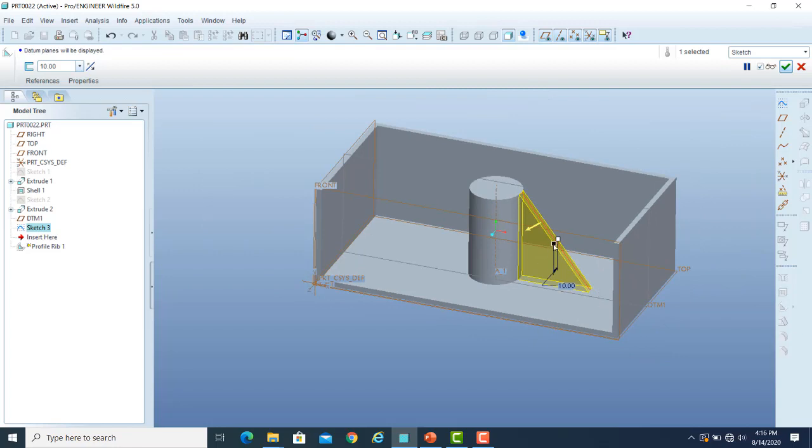So now let's look at what happens if I increase the thickness of that rib. The maximum thickness that you can give to this rib feature is the radius or diameter of that particular circular region. So if you exceed that, it is 50 units, basically the diameter of this circular block. So if I go beyond 50 units, you now have an open region in front of that particular thickness, so the rib feature again will not be generated. So this is how you can use the rib command.